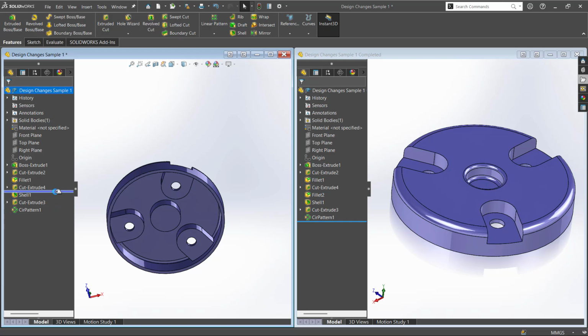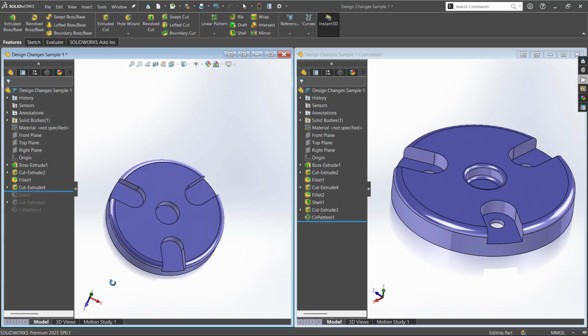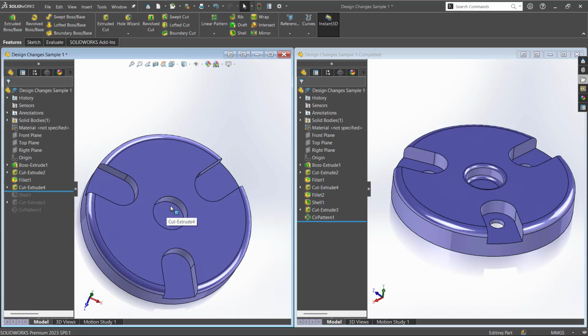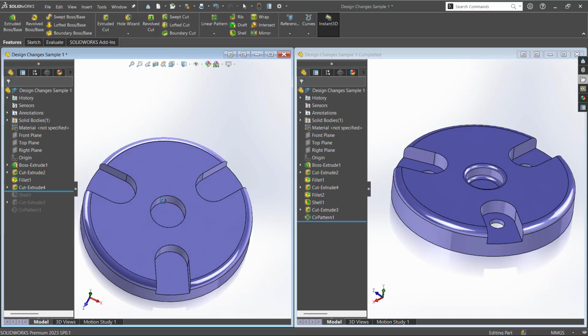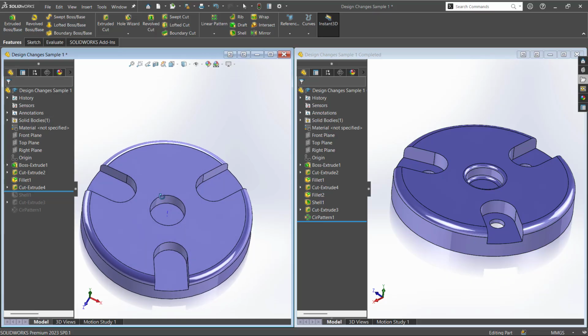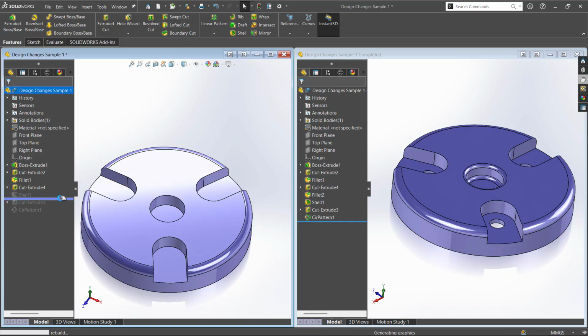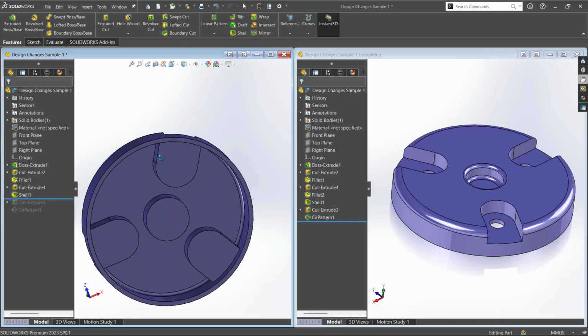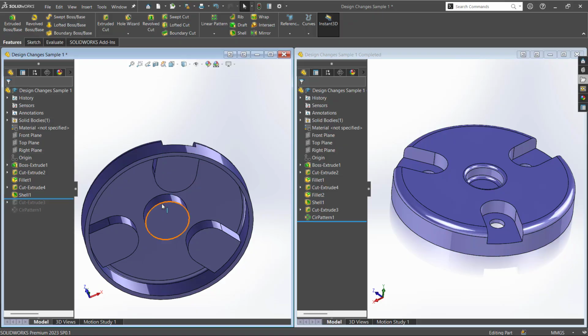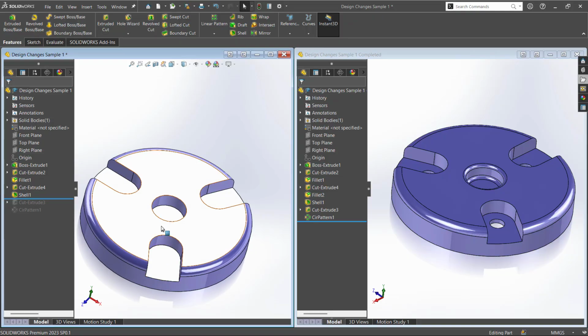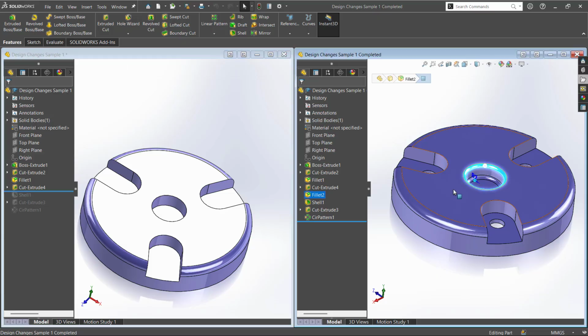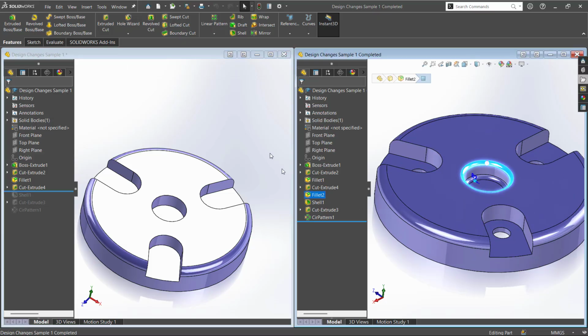Now if I go back here, as I said, the feature is created already, right? And then we have the shell. Now the thing is, if I create a shell now, it will capture the corners, right? So now I can apply the fillet here directly. What would be the fillet? If I just select here, it shows me the fillet value. It is exactly radius 2.